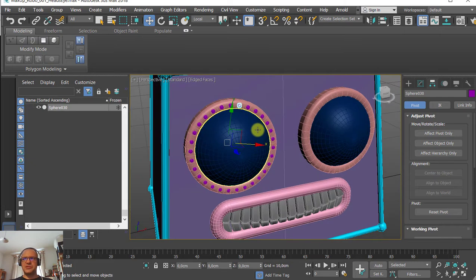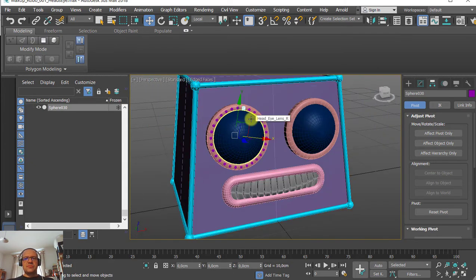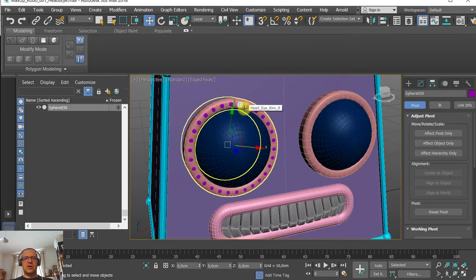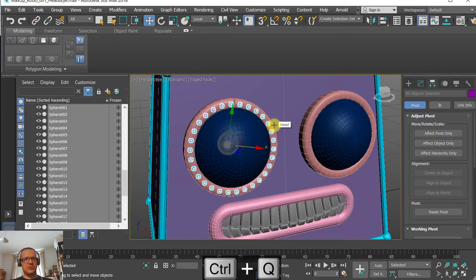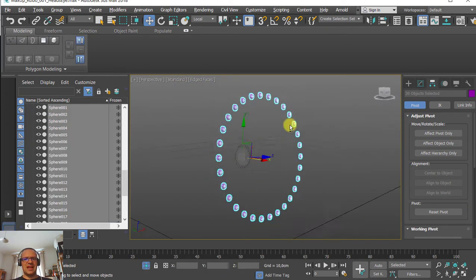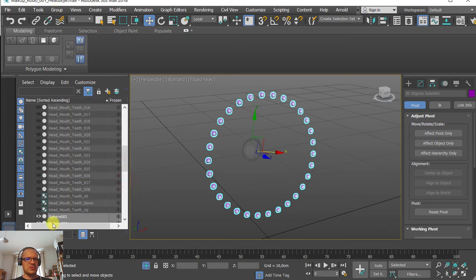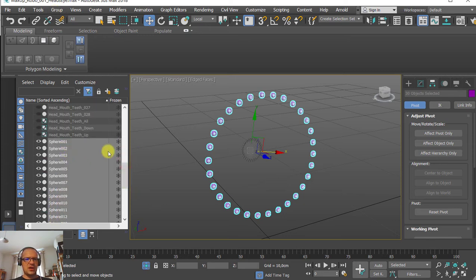Okay, it's pretty nice. Now, if I want to make a group, how to do it? Select only one, press Ctrl Q, Alt Q to isolate to make sure that what you selected is really what you need. And then you can go in and, excuse me, I was sloppy, but I don't want to go back. So before I make my group, I have to solve this problem.